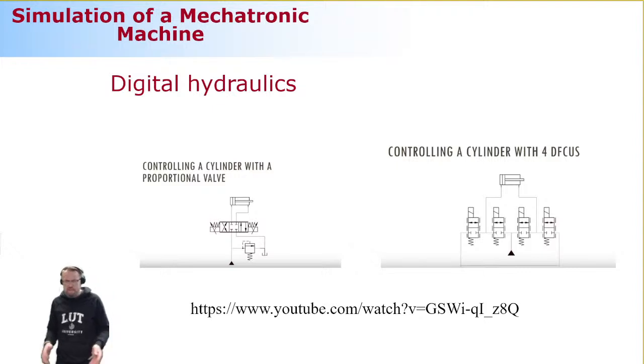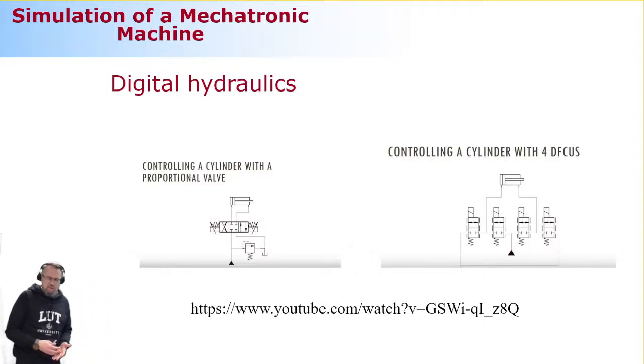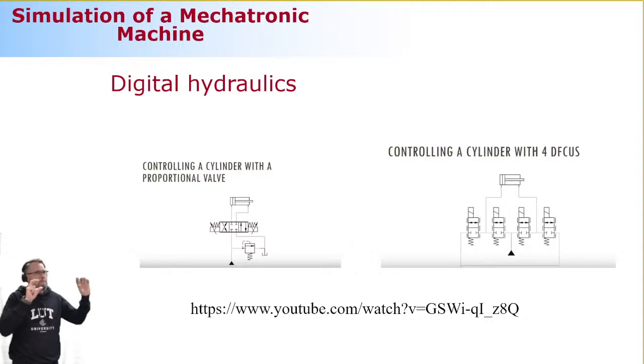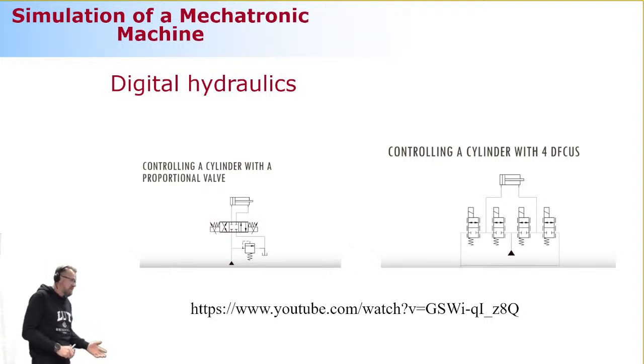Now, you recognize that conventional hydraulics is all about how to move this spool back and forth. It's based on the spool closing and connecting ports differently. They can be moved mechanically by a stick, or more often they can be moved by magnets, or by pilot drives and so on. There are many different opportunities, but there are still moving components that can have multiple different locations, an infinite number of locations to be specific.